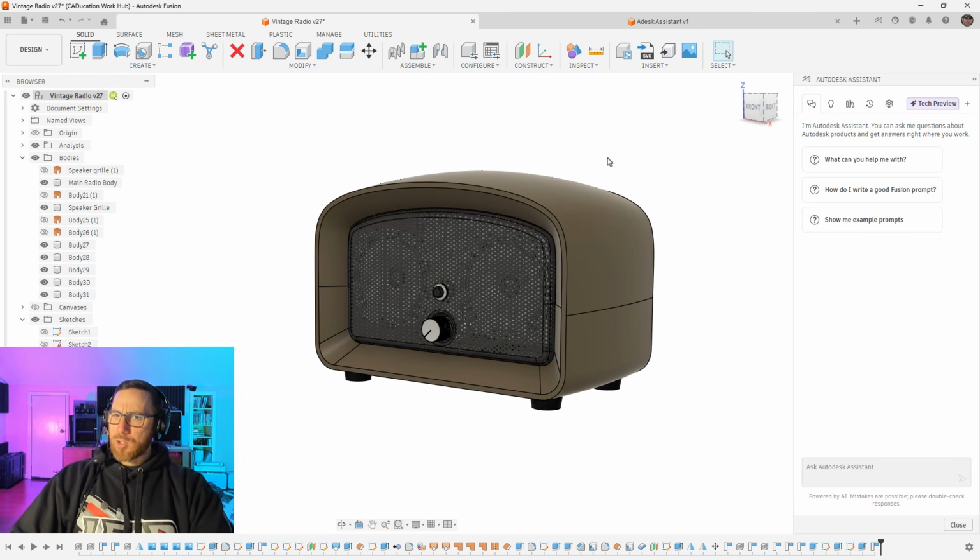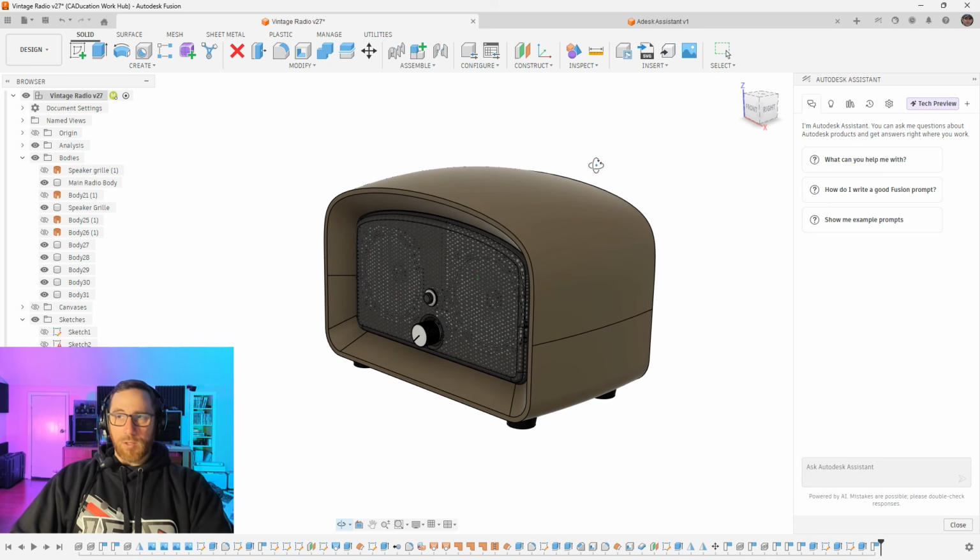Other things like changing all the materials in a large assembly. So if all the parts are ABS, but they need to be ABS PC, going in and having it find all the ABS plastic parts and changing them to ABS PC, that could save you some time. These are also things where, at least currently, while this Autodesk Assistant is running, you're not locked out of your design, but you really shouldn't be doing any other design work while it's working. It's like if you do a local render, you're waiting till the render's done until you can do something else.